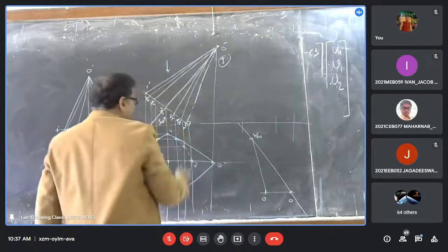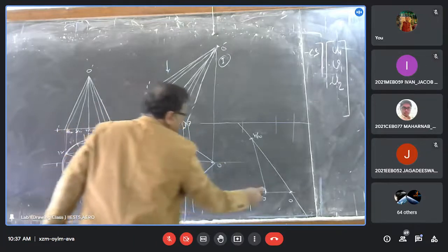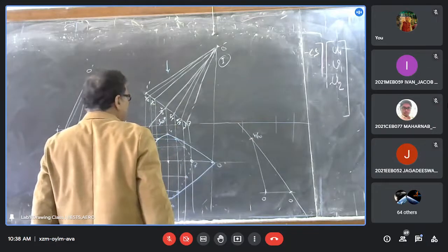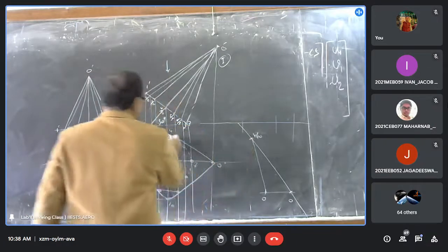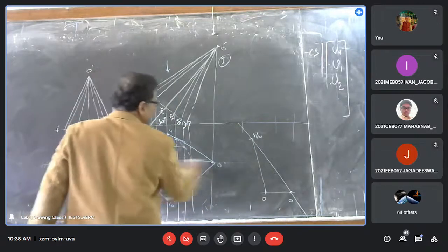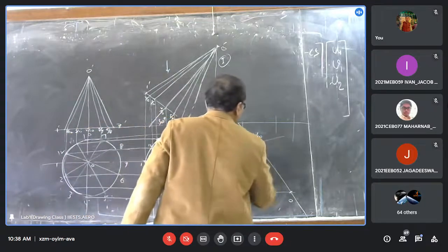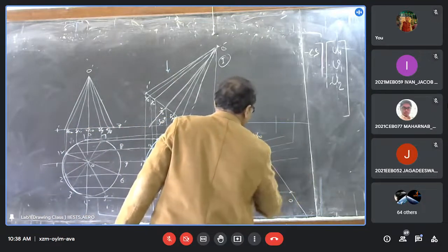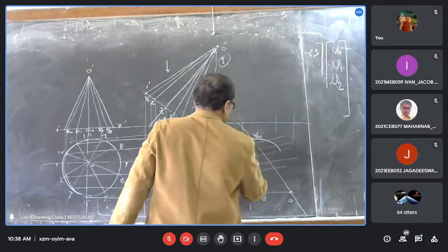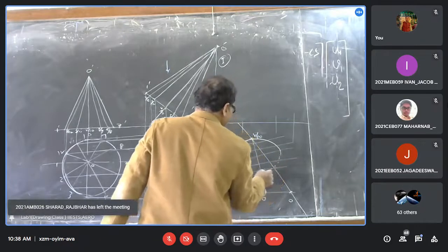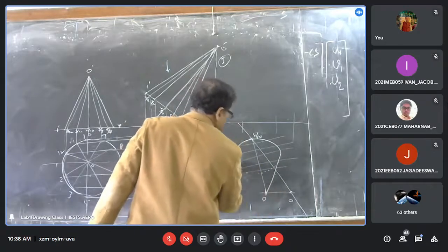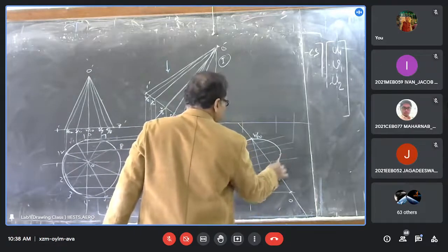So, then by putting this O, that 7 here, we should copy this figure. How? At the same point, there are so many parallel lines. In this line, you should draw a parallel line like this, perpendicular to that one, and locate 12 points here, and draw this ellipse. This part is dotted, the inner part, and then draw the tangent line. This copying of the figure is completed.